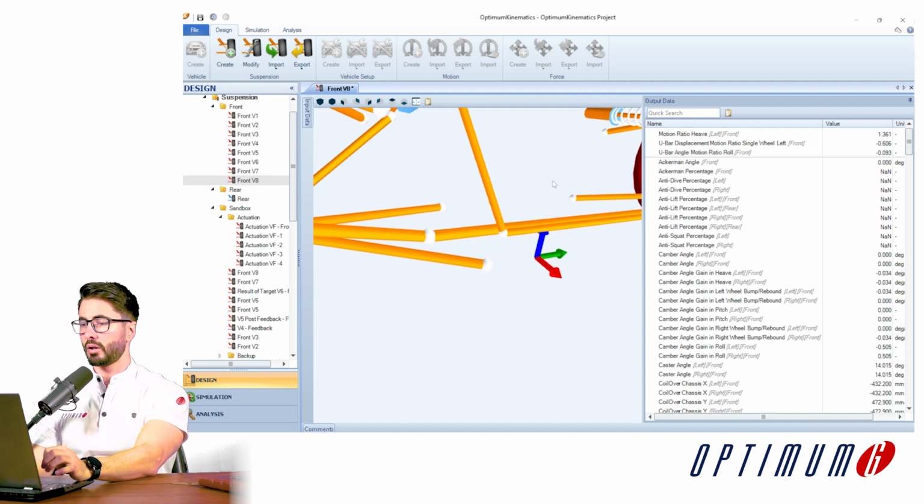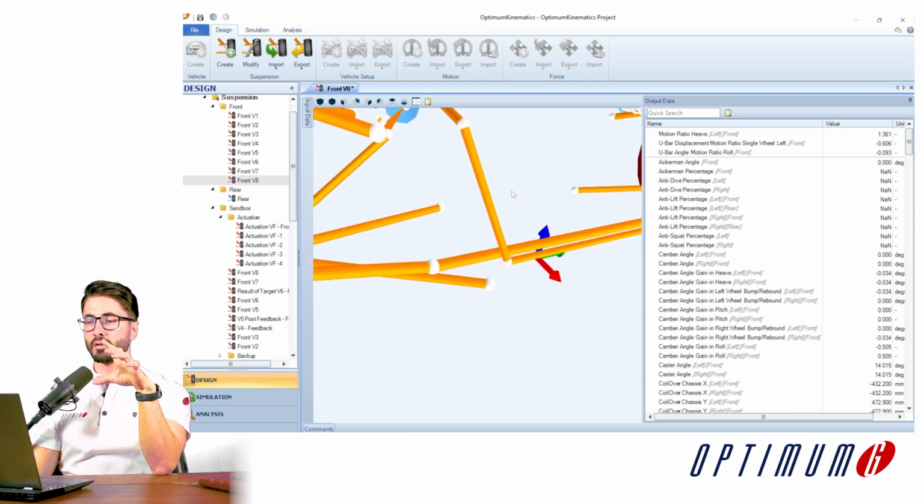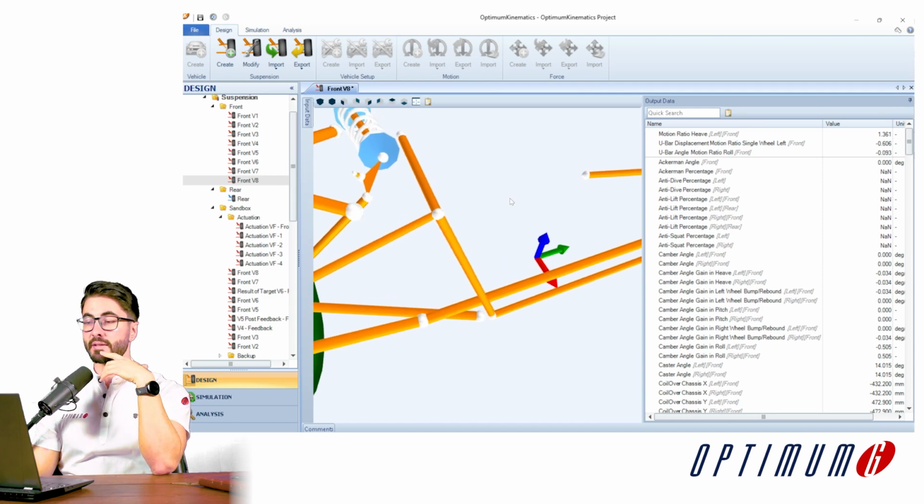Alright, so we are getting a lot closer to 0.1. I lowered this pickup point, the blade got longer, and then we increased the motion ratio. So I can keep running iterations to see where we get, but since later we're gonna use the optimization, I'm gonna say that I'm happy with this. Before we move forward, there is something extremely important.